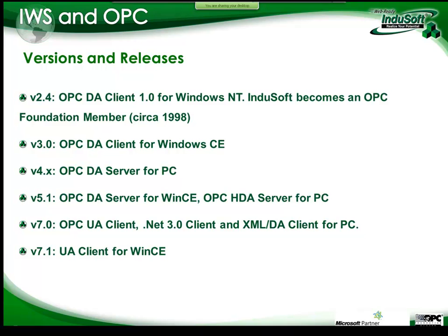On version 5.1, we made the DA server available for Windows CE as well, and we made our historical data access available for PC. So all the trend history information that is stored using InduSoft Web Studio, we make available for HDA clients, so historical data access clients as well.